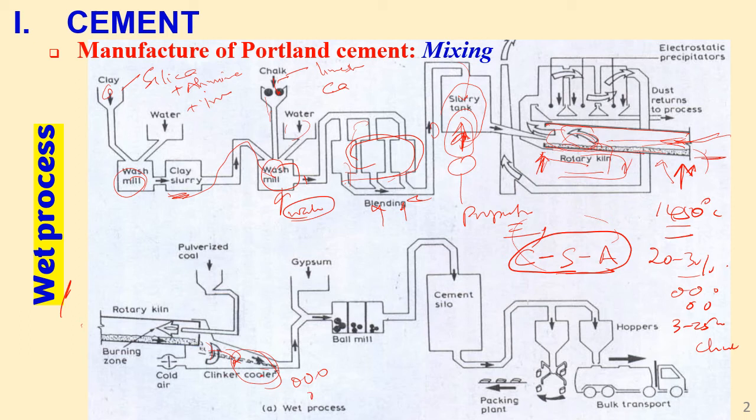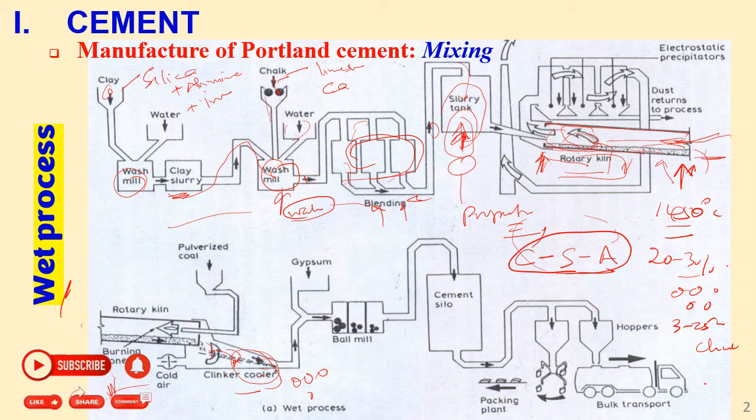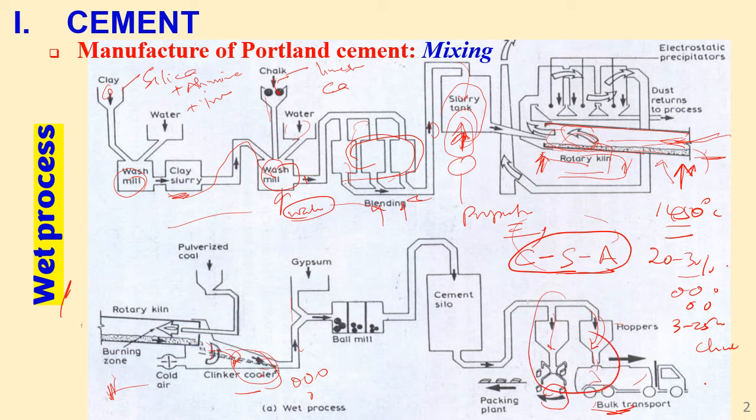And now from here, the second part from the rotary kiln, going all the way to the production, is similar whether you are using the wet or dry process. So let's finish the process here, and then I can mention something about the dry process on the upper end. Once we have this clinker, it's allowed to cool, and then you see these are pellets, but the cement that we are getting here, you can see these are either bulk storage, bulk transport, where you have seen these big tankers which transport cement in bulk. So these are hopper loading, or we can be packaging it in bags. This is a packaging section in the packaging plant. This is a cement silo. This is a storage of the cement.